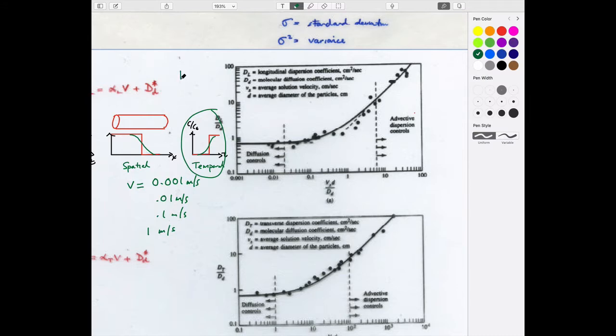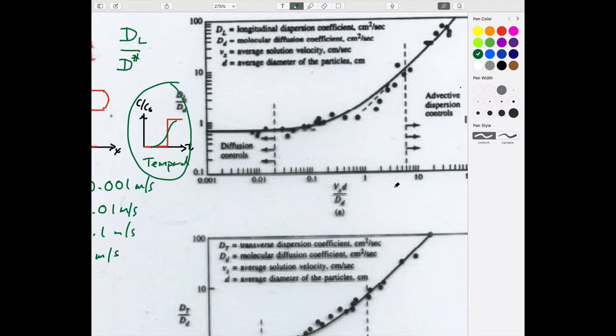And then this effective longitudinal diffusion coefficient you get, you do two things. You divide it through by the diffusion-only diffusion coefficient, and you plot it against the advective velocity, which you know because you run these experiments and applied it, the length of your specimen, which you know because you run the experiment, and the magnitude of d star, the diffusion coefficient.